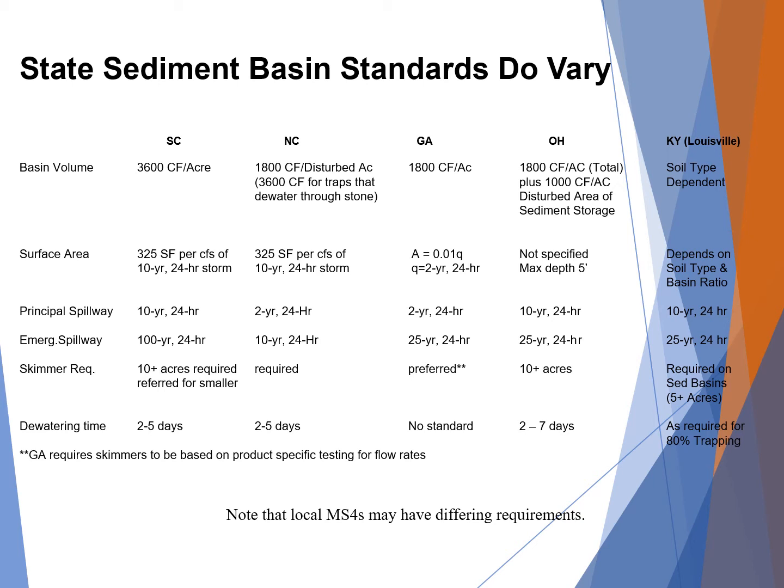So as you can see, standards for sediment basins do vary among states, and it's important to be aware of the states you're designing in and get those specific requirements. In addition, local MS4s may have differing requirements. Typically, they are slightly more stringent than the state requirements if they have to meet certain standards or have certain concerns in their area.